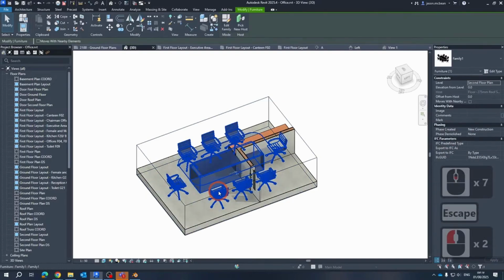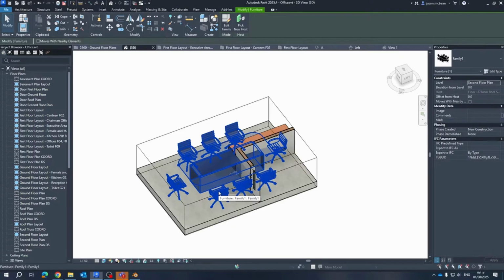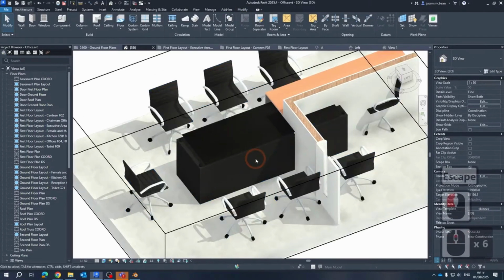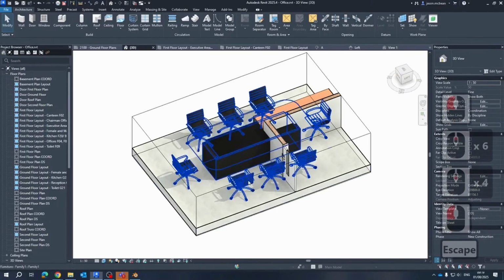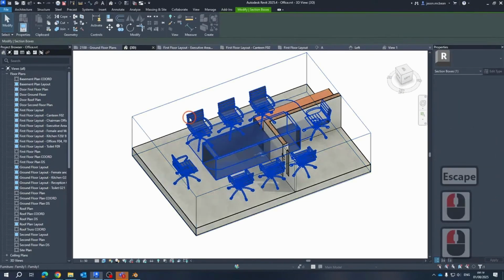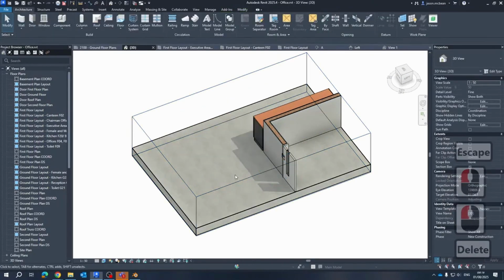Okay, because the model's dumb, it doesn't clog your Revit model full of unnecessary information. In essence this is just a mesh. It'll just represent correctly, but in theory there's no data, so it'll keep your models alive. So this is a great workflow to start adopting for these types of objects. Furniture, where you're not using BIM information, is merely an object to illustrate a furniture piece. Okay, so